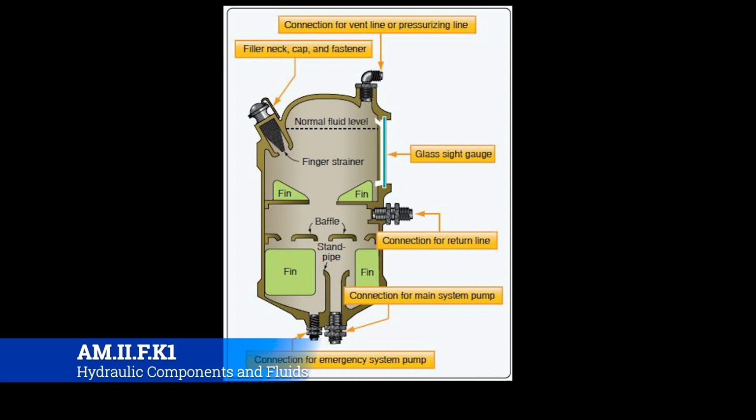You also want to make sure that the conditions are correct, because I'll give you a story. This isn't a hydraulic system, it's a helicopter transmission, but it serves the purpose. On the OH-58, you only wanted to service it when the transmission was cold, because the transmission oil would expand when it got hot. So if you came in and said, look, the transmission fluid is way too high because it was hot, then you would drain it all out, and then you'd come out the next day, and now it's way too low because it got cold and contracted down.